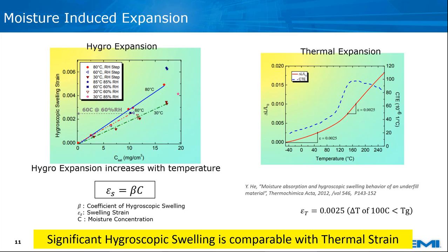We cannot measure up to the process temperatures used in the electronic packaging assembly process. This is because it is very hard to maintain a high moisture concentration environment in a lab above 100 degrees C due to rapid moisture evaporation. Next page.